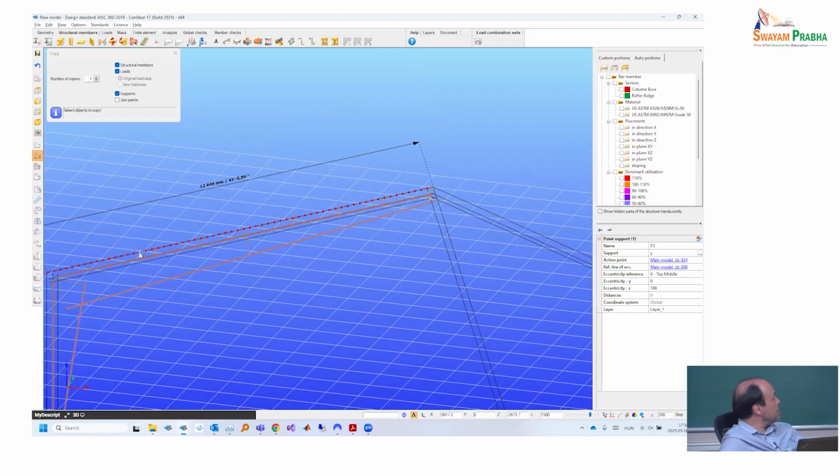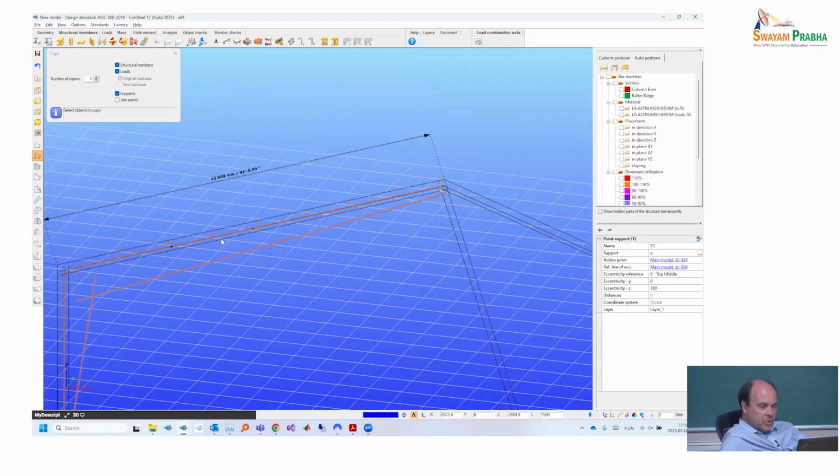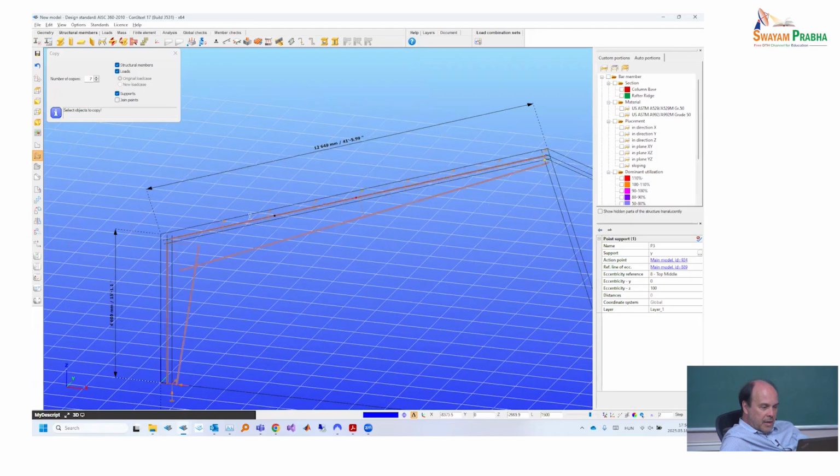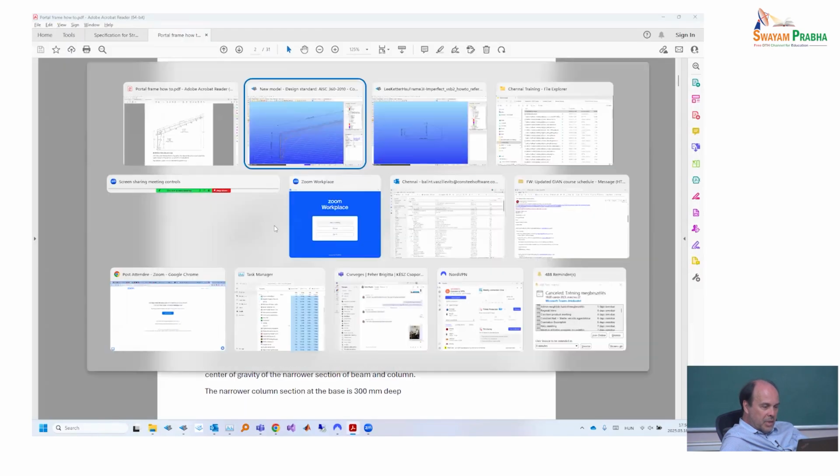If I don't want to see these many dots at 200 millimeter anymore, I change the D to turn to N, and I keep maybe the N equal 2. That means that only the middle lines are shown. So now I here have many supports, and then I have one more additional at 1 meter.